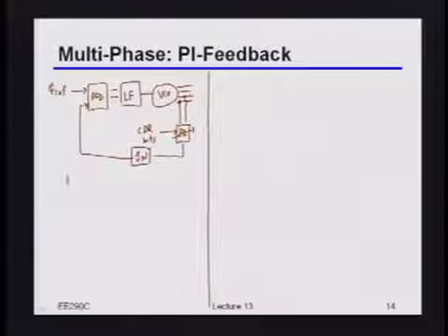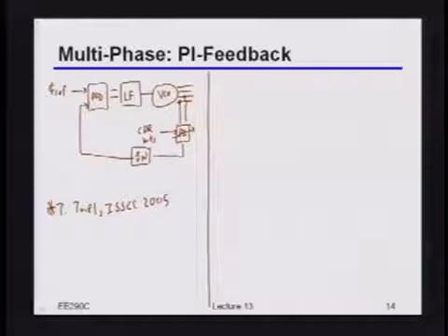Okay? So this particular idea, I believe, was first published by some people from IBM in Zurich. That's Thomas Toifl, and I believe this was in ISSCC 2005. So fairly shortly after the previous work that I mentioned. Okay, so this indeed works pretty nicely. Although notice it's not too horrible, but it does introduce some extra high-speed hardware, in the sense that you have this phase interpolator that's still working at whatever the clock frequency actually is.